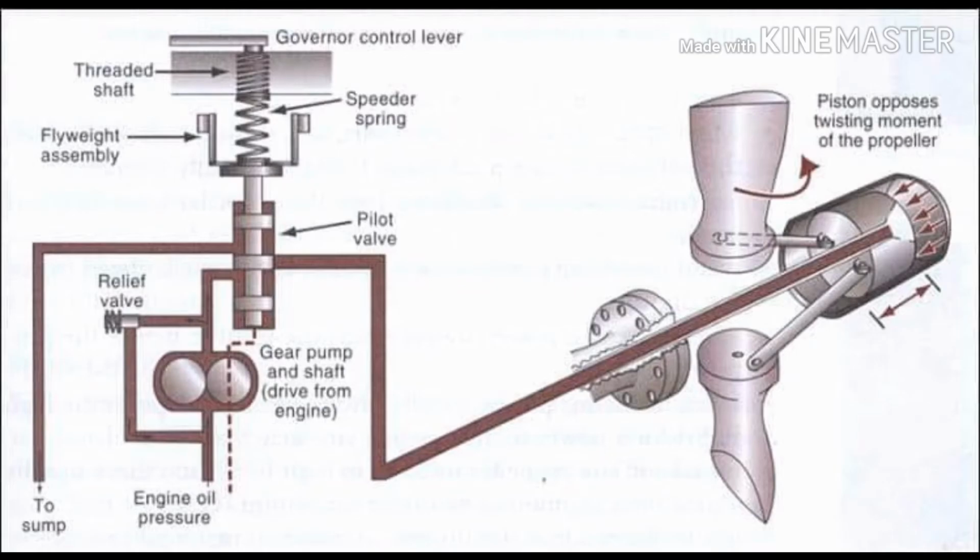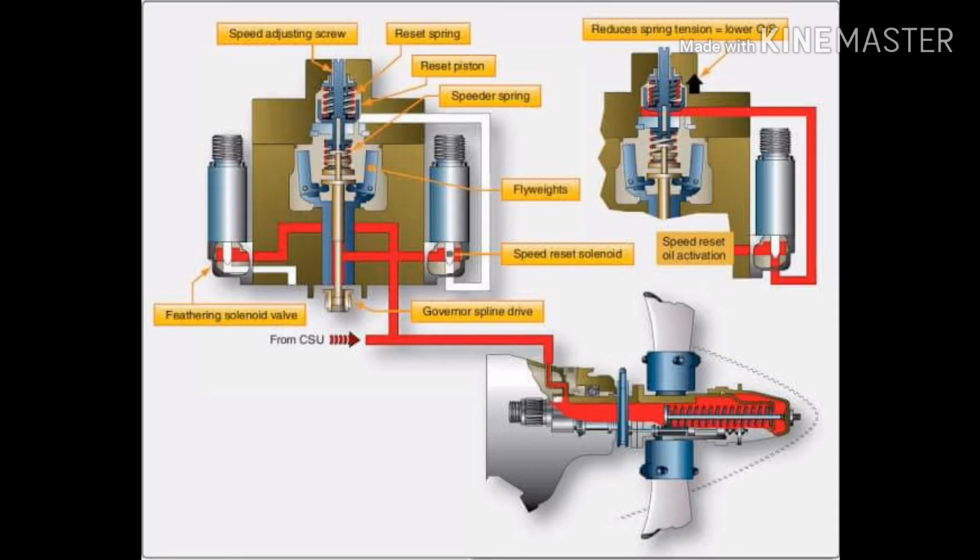An improperly adjusted governor can shorten your engine's life. If engine speed is not controlled, the engine will destroy itself. Never run an engine over speed, especially without a load attached to it.